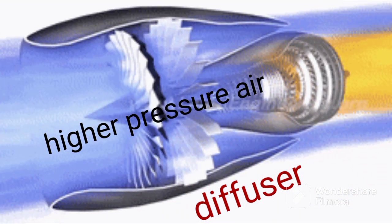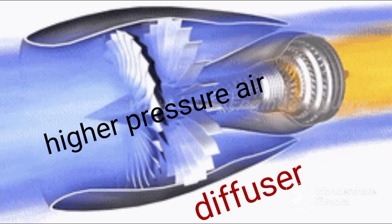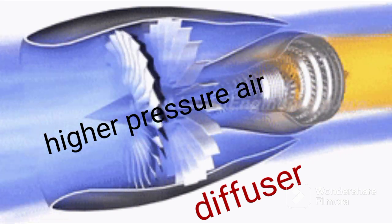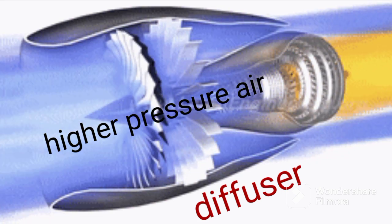Number 2. Diffuser. The diffuser is a component in a jet engine that helps to slow down and increase the pressure of the air entering the engine. Its main function is to convert the high-velocity, low-pressure air flowing into the engine into a slower, higher-pressure air stream that can be more efficiently compressed and ignited in the combustion chamber.